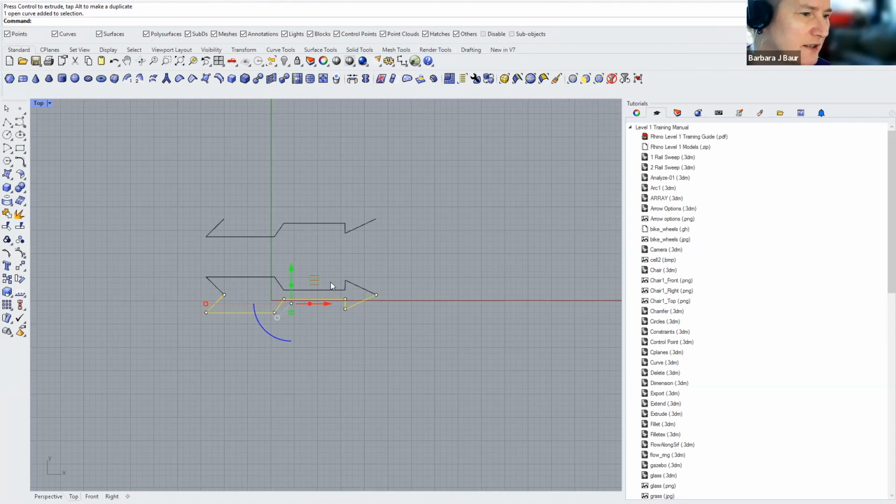All right, so I've got these two curves here. What am I doing here? I'm going to drag over the two of them to select them. Remember, there's a couple different ways to select things. If you drag from left to right, it's anything that is completely contained in the window, like only the top there. But if you drag from right to left, it's anything you touch. So we touch the two ends of that, and there we go. Both of those are selected.